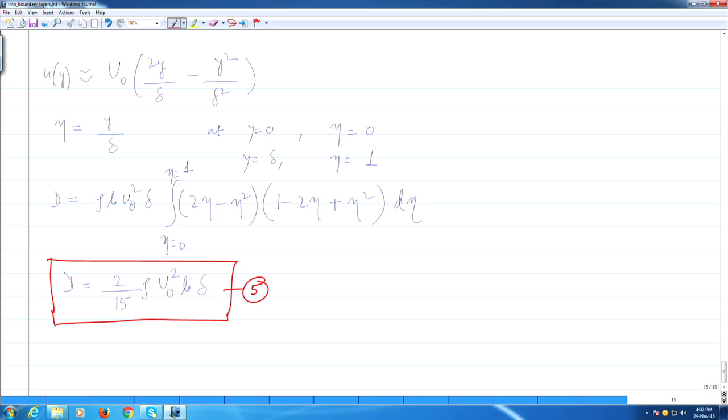Now, this delta is the height of the boundary layer at a certain point, and then we can calculate drag. So, drag basically depends on the height of the boundary layer. It is very important to mention here that this delta will be different with x. So, as we move along x, delta is going to change, right. So, we kind of know that.